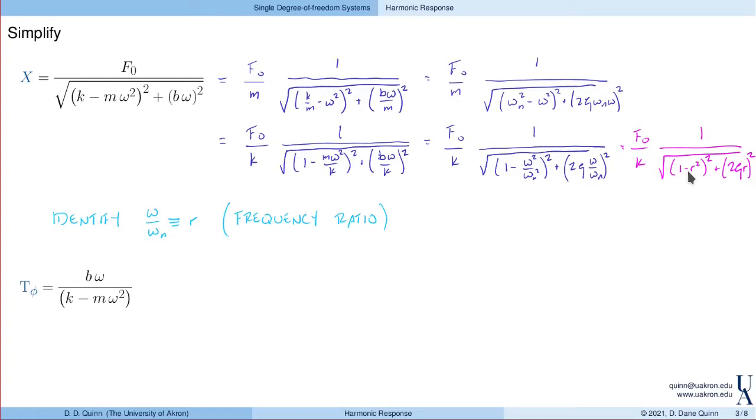You know, frequencies, we can think about those as related to time scales. So if the frequency is high, that means the time scale is short. High frequency oscillations, things happen on a really short time scale. If the frequency is low, then we have a much longer time scale. And so what we see is that the forcing frequency appears in this as its value relative to that natural frequency, or the intrinsic time scale of the system.